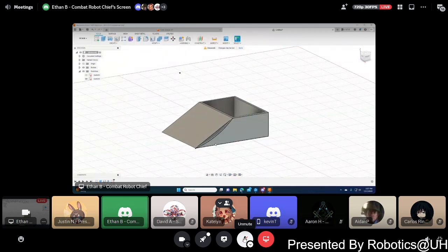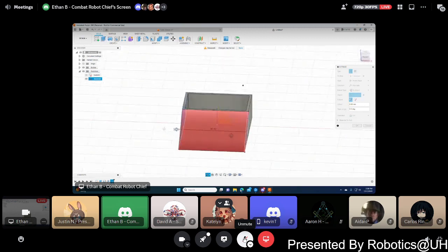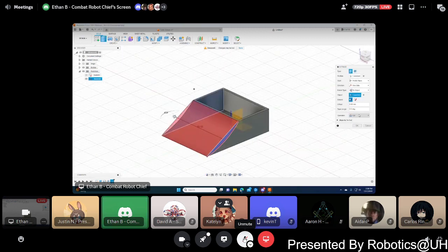I'll finish the sketch, and extrude on that, and I can cut it, right? I can select two objects and that would allow me to select a distance by just clicking on a relative object. And then I can select cut, but it automatically does cut if it intersects through geometry.